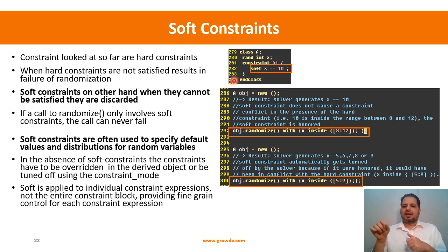Then when I'm saying randomize with, whatever value I've gotten from the command line, everything is fine. But if I want to pass, say it's an error injection type of scenario, a value of 12, my default constraint is taking a value of 1 to 10, but I want to pass a value of 12 for a certain error injection scenario. Now when I say inline constraint of equal to 12, as we know, inline constraints are additive.